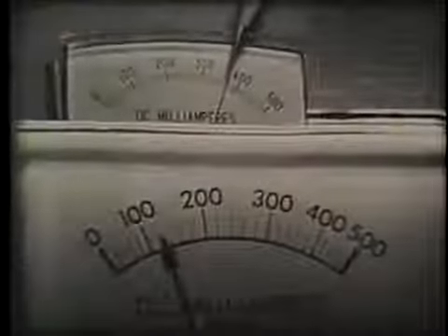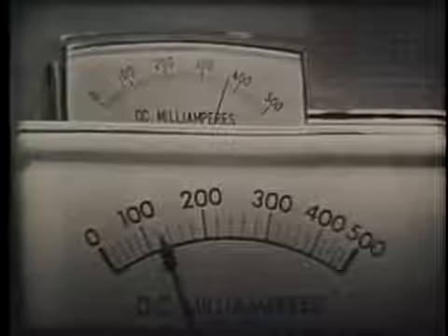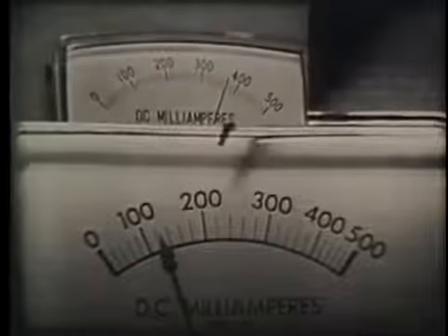Now, watch the total current indication when I close this switch down here. It increased. But why? This is because we added a parallel branch. This second branch is now drawing current from the battery. And if we add this current and this current, we'd find that their sum is equal to total current.